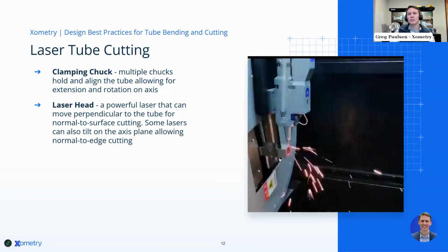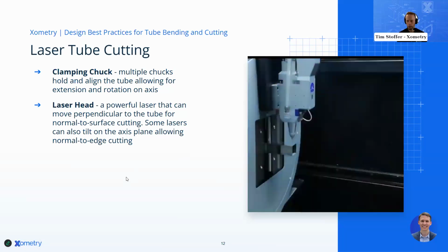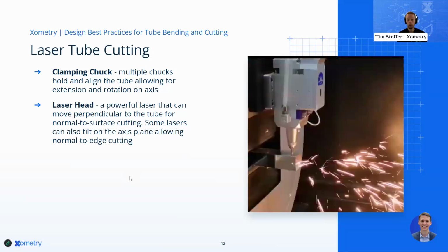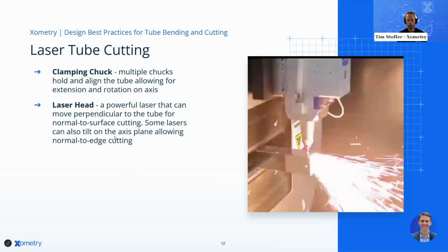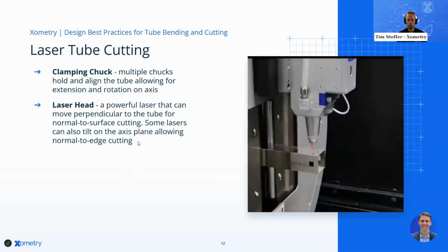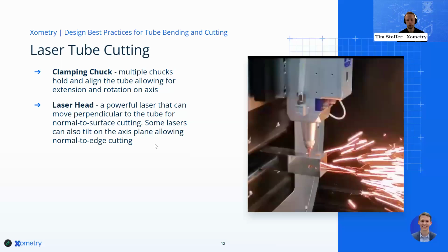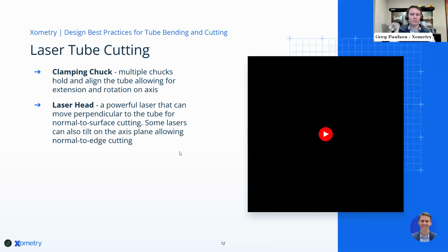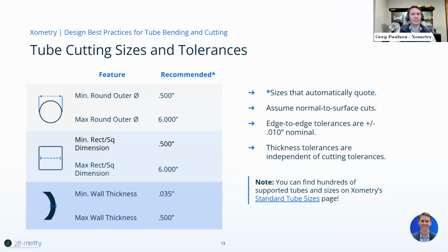Yeah, and that laser there, Greg, that's a fiber optic laser. That's common what our partners use. It's the newer technology, a bit different, more sophisticated, I guess, than the CO2 lasers that you see in sheet cutting. Absolutely. For example, in sheet cutting, I may use CO2 for acrylic or a thinner gauged metal. But even there, fiber laser has been taking over because you can put a lot of power in one place very quickly and move way faster. Your throughput is just way higher with fiber laser cutting.